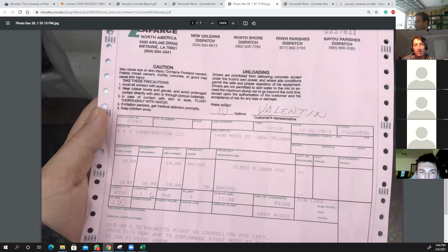And it is somewhere over here. If you guys see what time, 12:18. So there's a 90 minutes limit. If the truck is late more than 90 minutes, then there's a problem, because concrete starts setting after 90 minutes. So you have the right to refuse this order.